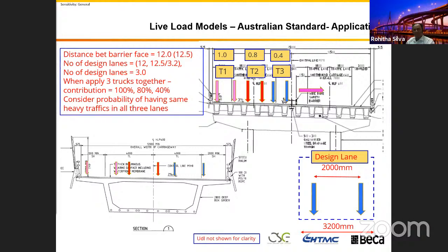When you design the bridge, the position of placing of the truck, you can place it. I will give you one example. You can see if you put this truck in the exterior end, you agree with me that will produce significant bending on the exterior girder. Therefore, I should push one truck or truck system to the end, right?